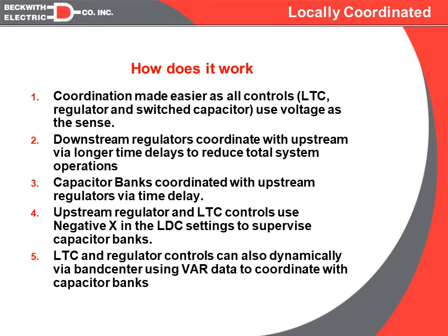So, we're going to coordinate the LTC with the regulators first of all, and that'll be done via time delay. As a general rule, the regulating device closest to the source should have the shortest time delay, and then we should add time delay for every regulating device downstream. We also want to coordinate the regulating devices with the capacitor banks, and this is most easily done if the capacitor banks are voltage controlled.